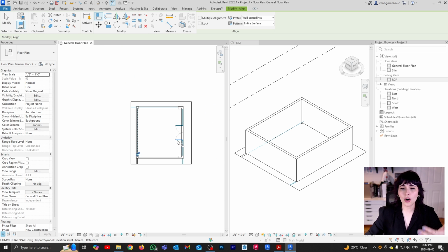this is that my AutoCAD drawing is serving simply as a reference. As soon as I'm done drawing this architectural shell, I will delete the AutoCAD drawing. I don't need it in the long term. This is not a live construction drawing. The building already exists. It was already built. I'm just drawing my own design in it. So because of that, I will not be locking these walls to the CAD drawing, because the CAD drawing is going to go away soon.